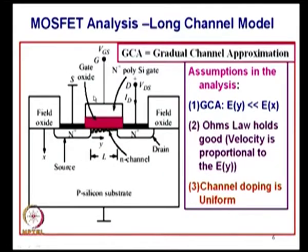notice we have taken only this portion of that, because that is where the transistor action is. And what does this portion do? The bottom portion, it is only mechanical support. After all, this region will be as thin as 0.1, 0.2 microns, but this whole thing is a wafer which will be 300 microns, 400 microns, depending upon the wafer thickness. Okay. If you have a 4-inch wafer, if I can say so, that is 100 millimeter diameter wafer, that will be about 400 micrometers thickness. So, that is to give an idea.